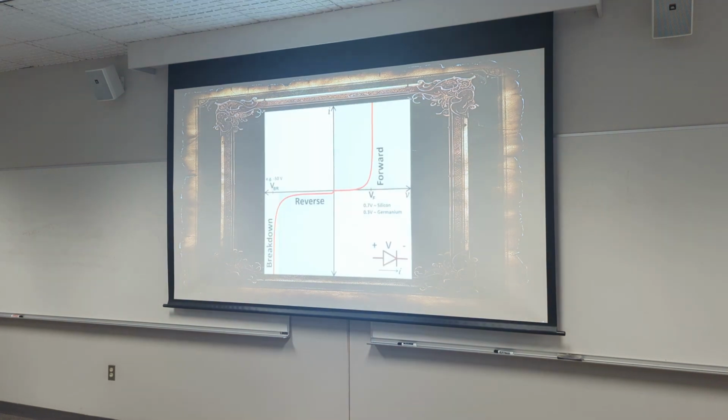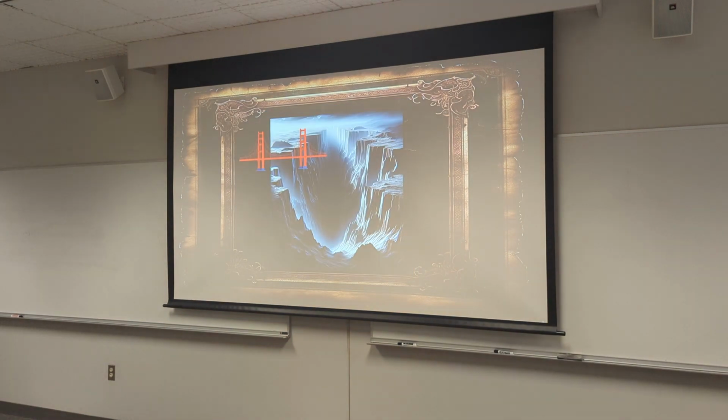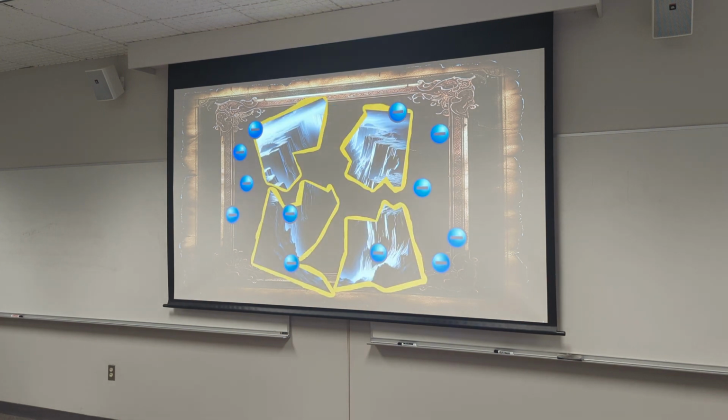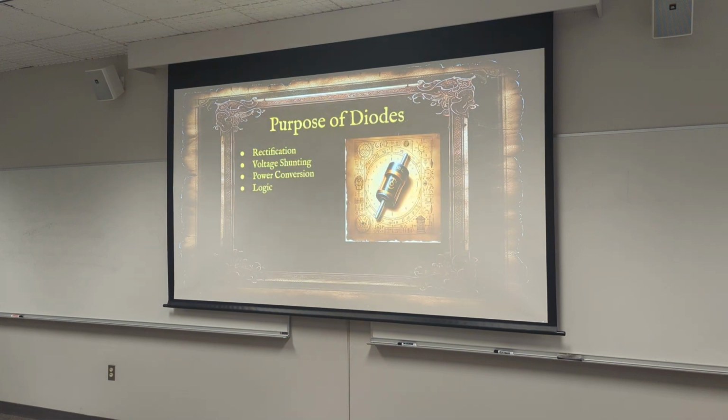Connecting a diode in reverse bias, here's a diagram. So as we apply a forward voltage, after a certain level, it becomes a short. But as we apply a reverse bias, it's like we're removing that bridge, and electrons start gathering on the other side. And when the electrons become so abundant, they will actually jump across in what is called an avalanche or a breakdown. Most diodes are designed to break before this happens. But there are a few exceptions, like Zener diodes, whose entire purpose is to run in reverse bias.